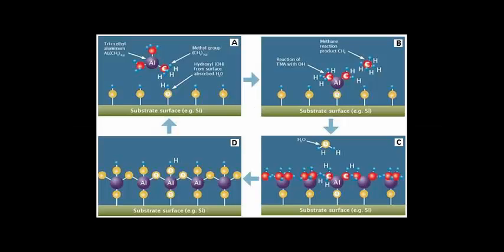First we chemisorb the substrate with TMA and then we purge the remaining TMA after enough TMA gets absorbed on the surface, and then we pass O2 plasma over the monolayer which got formed on the substrate, and then we purge away the remaining O2 plasma, and the two reactants react and aluminum oxide gets formed on top of the substrate.